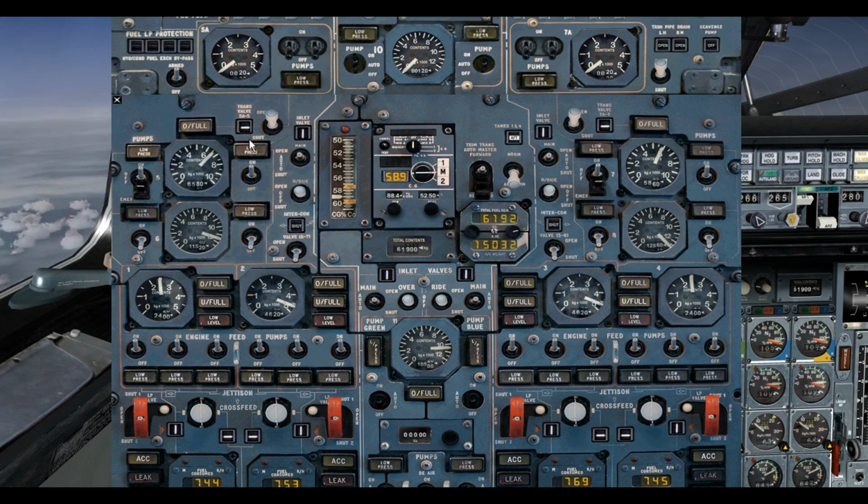I'm going to close the inlets, and I'm going to close the trim pipe drain. But we leave our aft trim indicator in aft, and you'll notice that the fuel weight in tanks 1 and 4 has moved down, and it'll continue to move down to about 2,050, I think. I'm going by memory here, but it'll continue to move down, and then it'll stop for the remainder of our cruise.